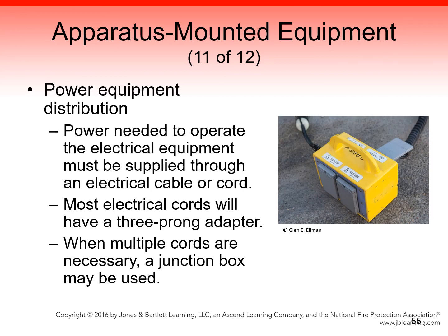Power equipment distribution. The power needed to operate the electrical equipment must be supplied through an electrical cable or cord. This cord must be waterproof and provide durable insulation. The cord that is used in everyday household appliance applications is not suitable for the fireground. Always purchase quality commercial-grade electrical cords and adapters for fireground use.